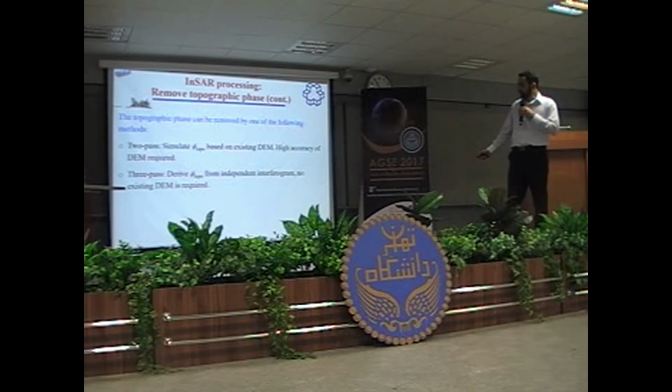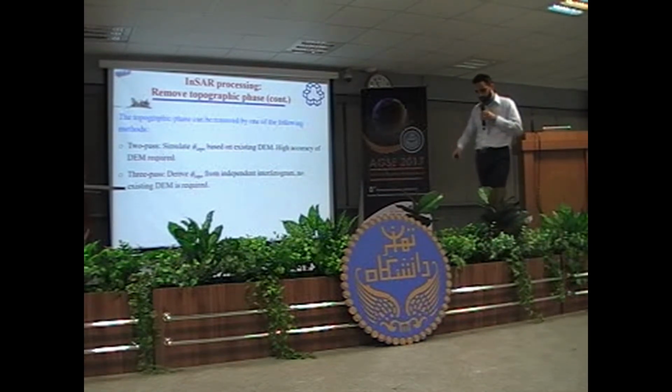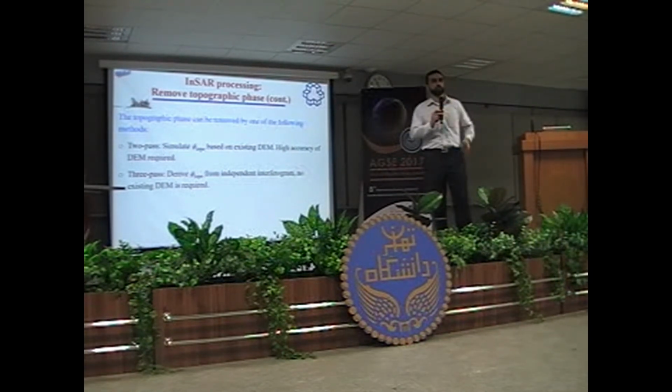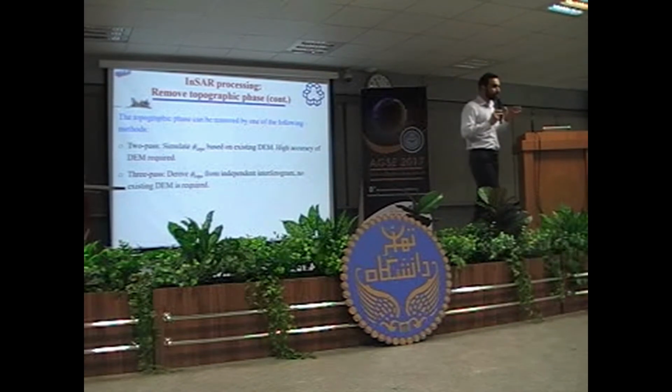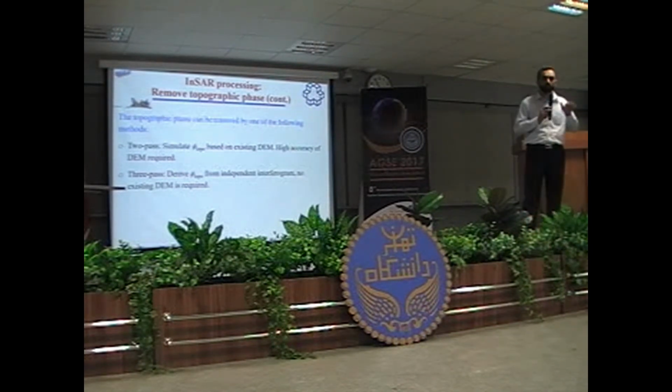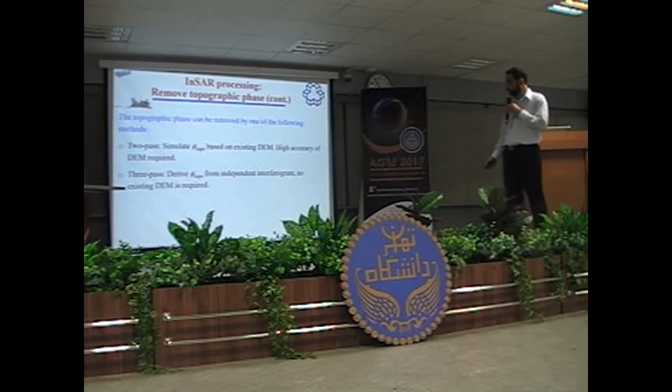So basically, if you have just two passes, the topography phase can be subtracted using the existing DEM. So if the purpose is to calculate the subsidence, you need to have the digital elevation model in advance from the area to remove the topographic effect.